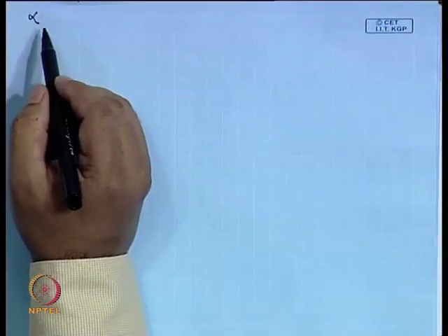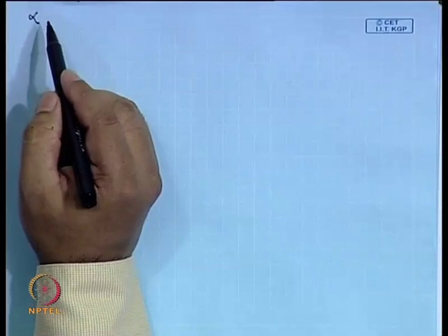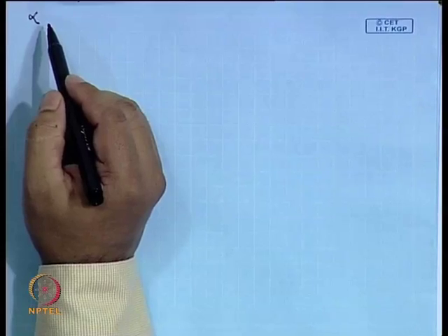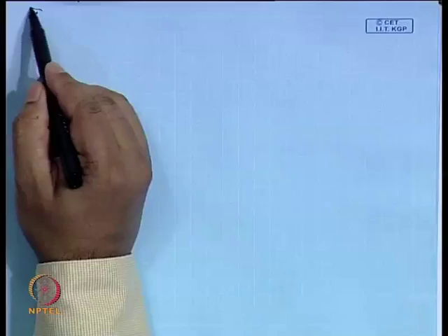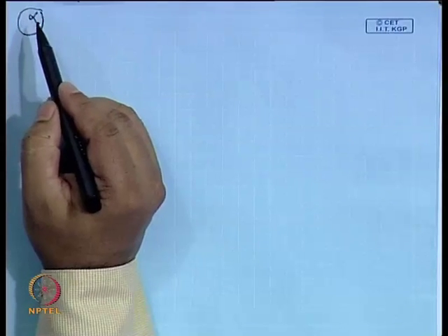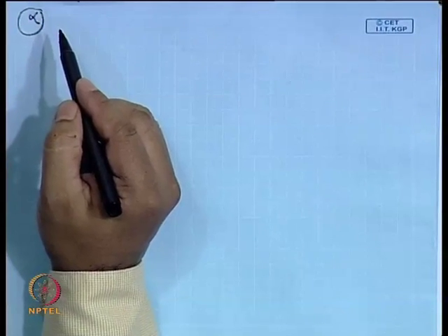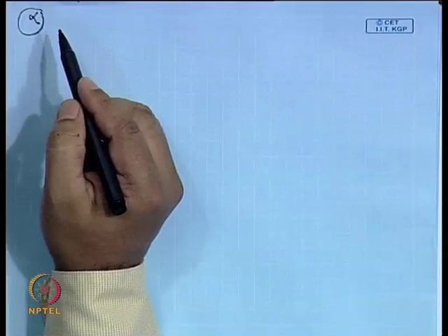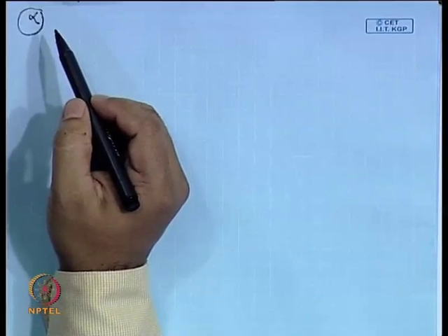In the last class, we have been discussing mixing, and more importantly mixing quality and mixing effectiveness. We defined a term called alpha, which changes from 0 to 1 in the mixer. Alpha is equal to 0 at the inlet, when the flows are considered completely segregated, and alpha should be equal to 1 at the outlet, so that you can consider mixing to be complete. This is what we define as mixing quality. If somebody asks how good the mixing has been done, alpha is a good parameter for that.